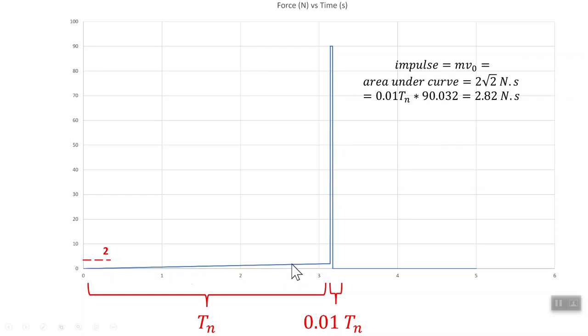So this is why after one period, the force is applied and it moves the mass to the location of 0.5 meter, which means at the end of this linear time variation, you're going to have 2 newtons applied to the mass. At that instant, we give it an impulse over a very short period of time. If you go back to your vibrations book, you see that the area under this curve is called impulse, and it's m v naught. So if m is 1 and this impulse has the correct area, then you're going to get the initial velocity out of that. And then we drop the force.